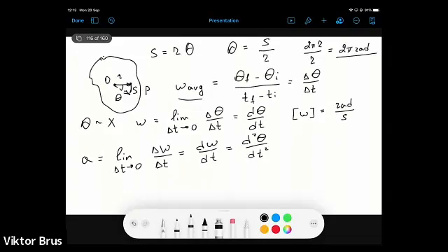So it will be necessary to define very many points with different vectors. So in order to define one unique vector, which will describe in which direction, clockwise or counterclockwise, in the given frame of reference this system is rotating, we operate with the angular velocity vector, which is oriented along the axis of rotation in one or another direction. And the same stands obviously for the angular acceleration vector.